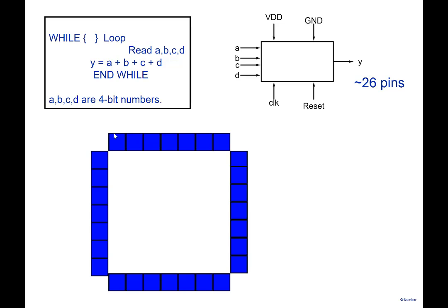And for our discussion for 0.18 micron, this is what is called the pad ring. We'll take the dimension as 70 micron. So each pad that you see is a piece of metal deposited on silicon dioxide, 70 micron here. If we design it as a square, 70 into... So we'll take it as 50, fine. To get the numbers right, we'll take it as 50. It could be 70 also. So 50 into 7 gives us 350 micron here.